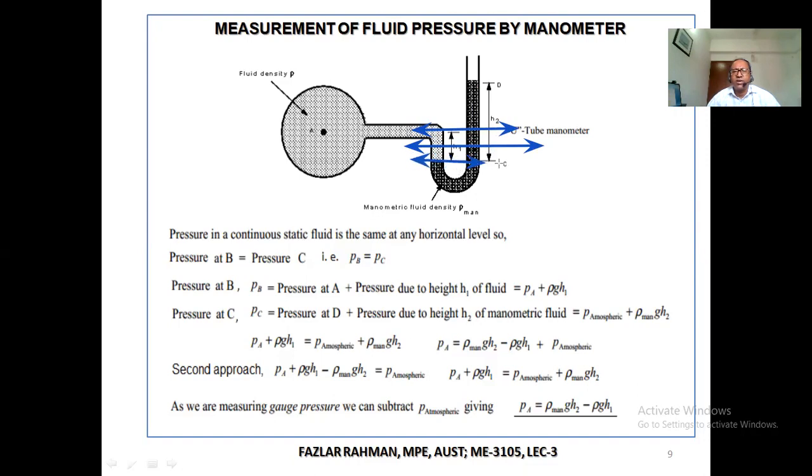But you can take it over here cleverly, because point B, I can consider it to lie in both fluids. Why am I not taking it at the bottom? Because there is no dimension. What is the meaning? If you take it at the bottom, then you need to walk down this much distance, then you need to walk up this much distance. Ultimately, no balance, zero. So why would you do the extra work?